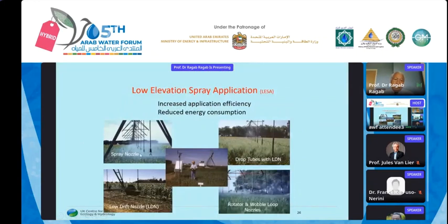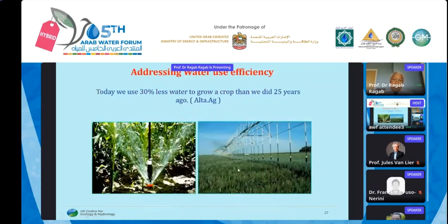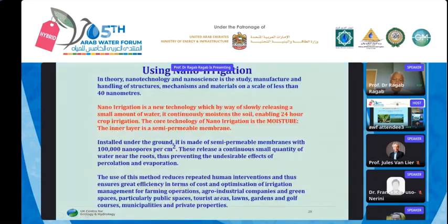The other thing that, of course, to use to increase the efficiency of the irrigation system is to use low nozzles very close to the surface, so as to avoid the wind drift and the losses by wind, and that's also useful for reducing the evaporation losses. And if you can see here, the nozzles are very close to the ground, it might be useful for poor quality water to use low nozzles closer to the ground for that reason.